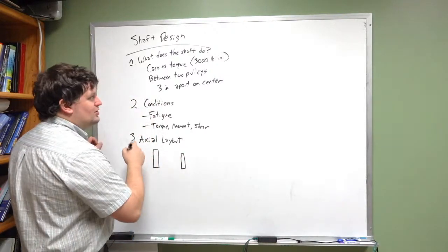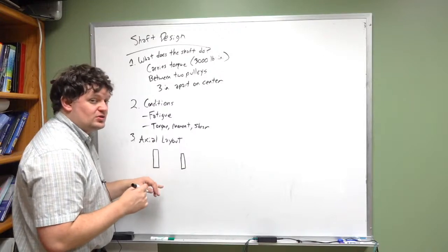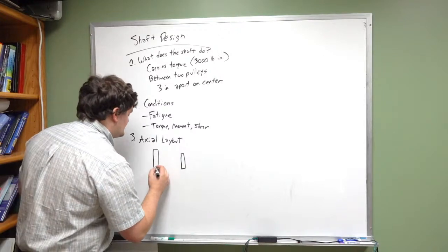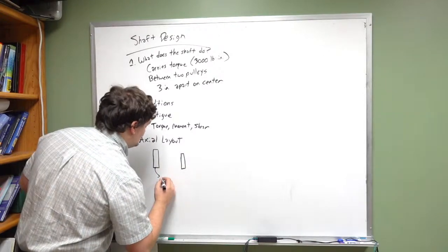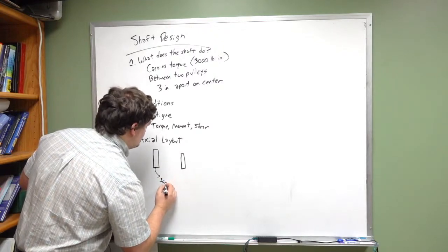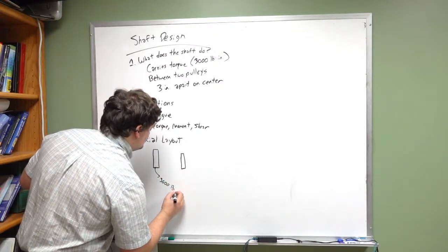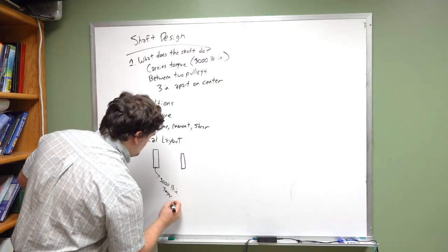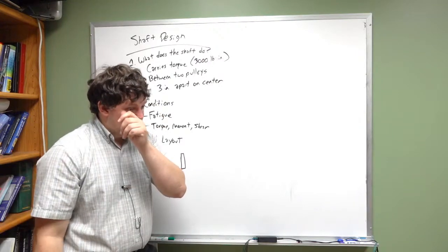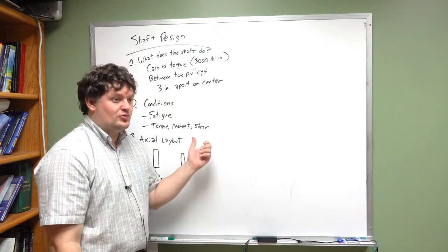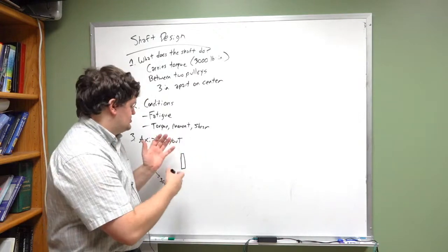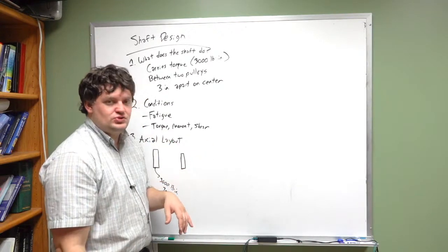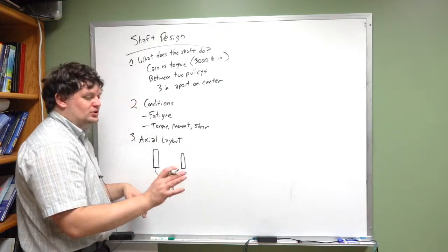And this pulley, regardless of the diameter, regardless of what it is going to be transmitting, 3,000 pound-inches of torque. Okay? Because maybe this is what's being output from one motor, and we're just gearing it down to this pulley or whatever.